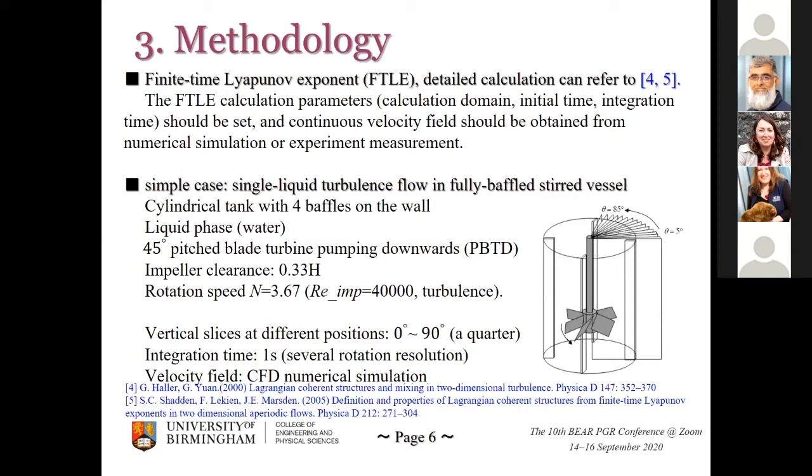Because in industry we have a conventional concept that the flow in the tank is axially symmetric, but actually in flow transport it's quite different. So we select different azimuthal planes, from 5° to 85°.